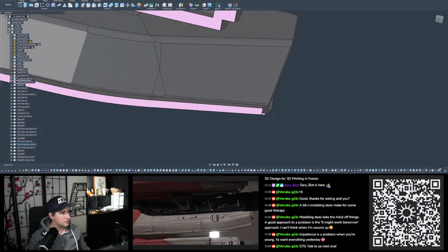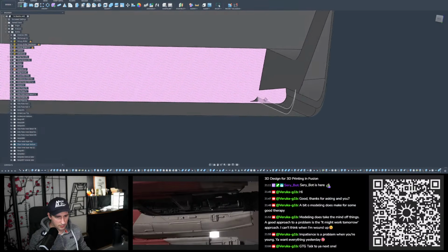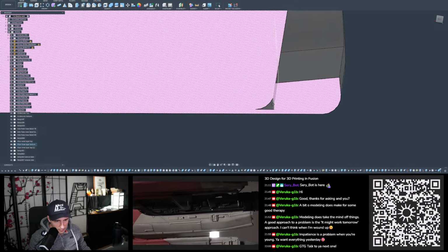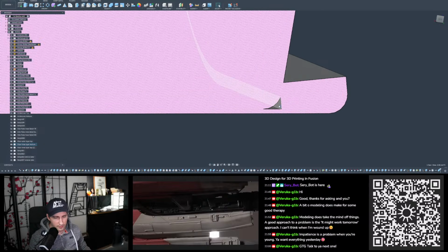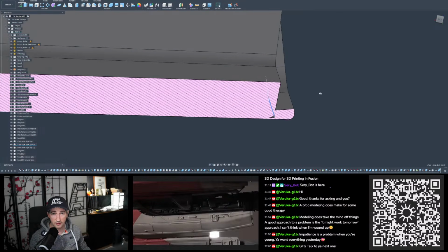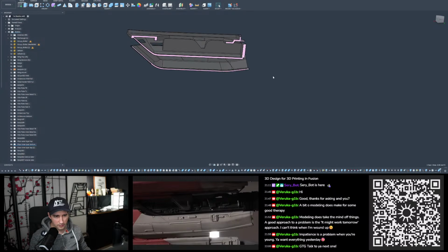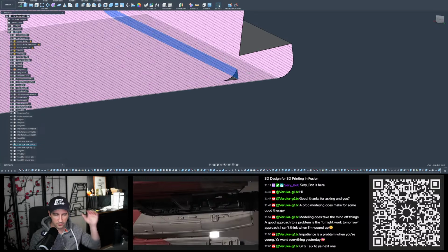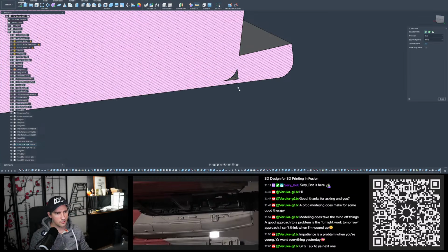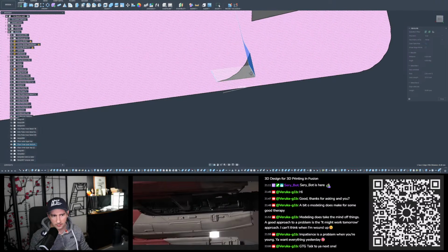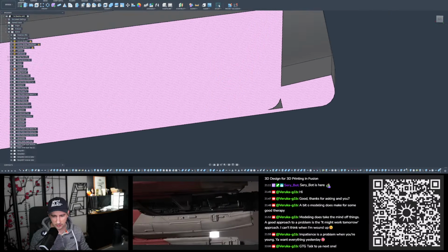Let's make a quick check. Yeah, this is what I was looking for. If there's a hidden cavity left, and there is. So I need to extend the extrusion by at least 0.3 millimeters, so make it a half a millimeter longer, and then we should be good.